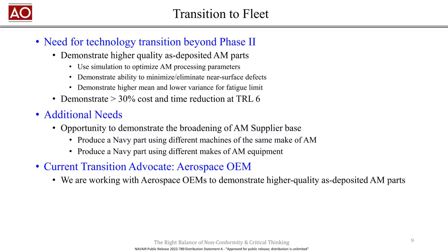We consider part geometry as a collection of interior and boundary regions. We account for upskin, vertical skin, and downskin features, local thermal conditions, hot spots, and provide options to minimize build defects.